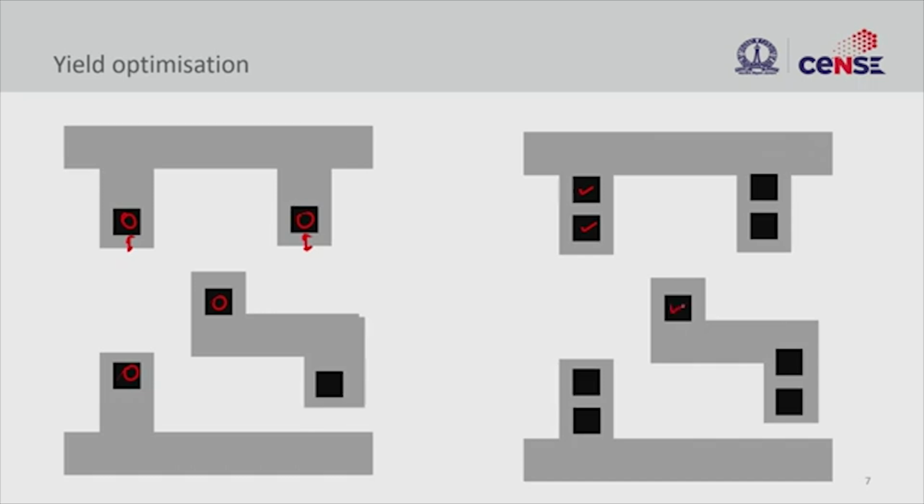As I mentioned, in some instances you may not be able to do multiple contacts, so then you just live with one, but make sure that your contact holes are reasonably spaced, and you have to live with that. But wherever you could add multiple contacts, we should exploit this so that you have a better yield, right?